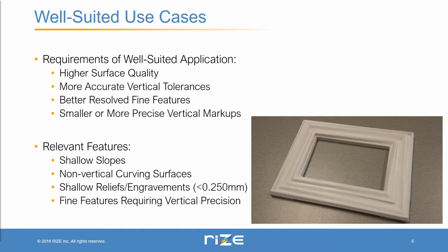So some of the features that may be present on a part that should also persuade you perhaps to consider using fine resolution include, as mentioned, shallow slopes, non-vertical curving surfaces, shallow reliefs and engravements, and fine features requiring vertical precision.